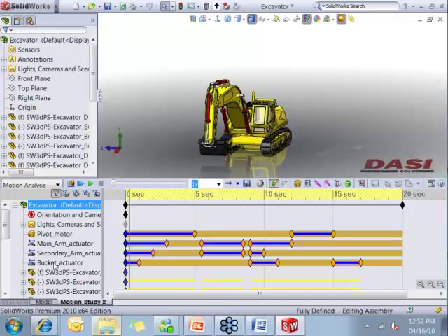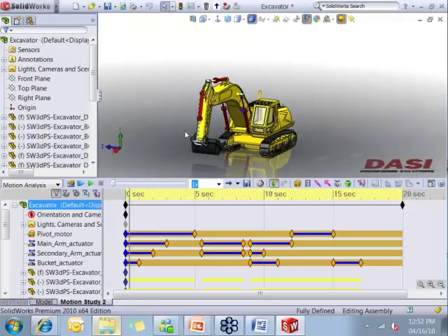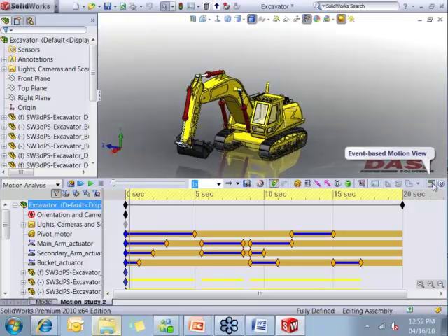The thing that you want to keep in mind with the paths that you put in for your components, don't forget about applying motors. Motors a lot of times will make the stability of your animation much better. I find myself using these actually quite a bit. In fact, that's another thing that I wanted to mention inside of the gripper earlier, but that's okay.